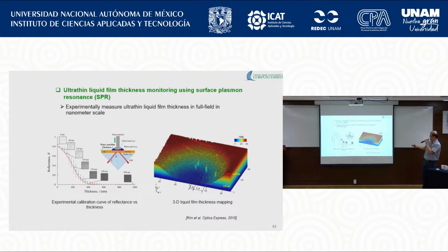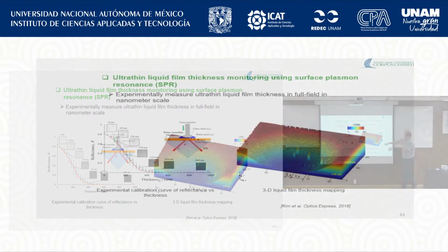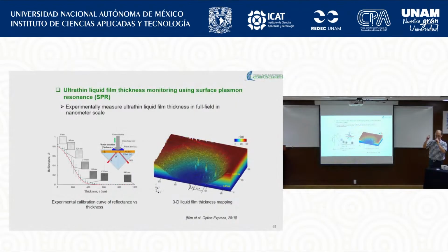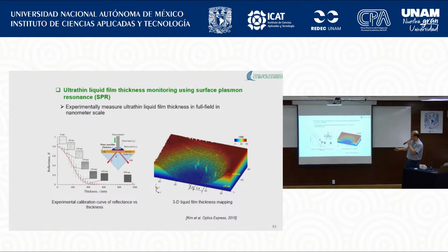This is the SPR result from the ultra-thin film measurement. We conducted an SPR measurement to show that liquid film thickness can be measured with 2.5 nanometer resolution. It's a very interesting result because SPR is a very simple technique, but its sensitivity is high.